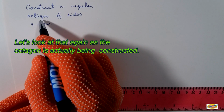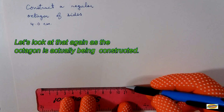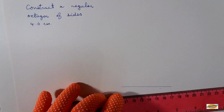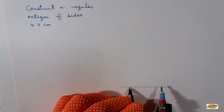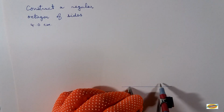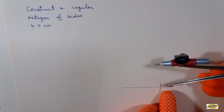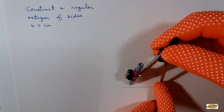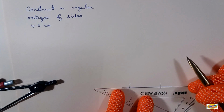Construct a regular octagon of sides 4.0 centimeters. So let's draw a construction line. Measure 4 centimeters. Near this end, place the metal point and make an arc like that. And then where that arc intersects this line, make another arc like this. Bold this piece of the line.